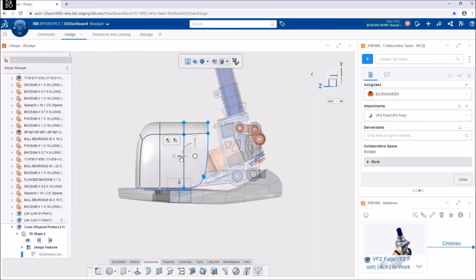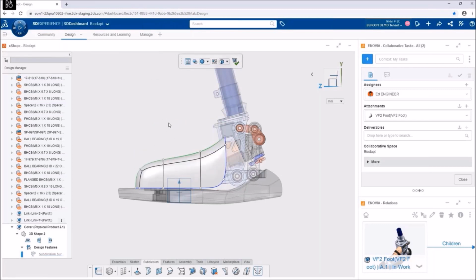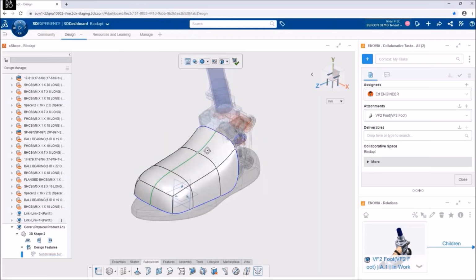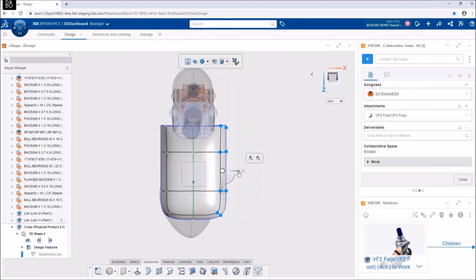I want to extend the length of that primitive, so I can select a certain portion and drag it. If you want to tilt, we give some draft, or I can say tilt the primitive shape at a certain angle. Also if you want to follow some arc, like if I want a shape like this, I can just trace a line, and the primitive will follow that shape. So it's looking fine. And now we will add some other features.